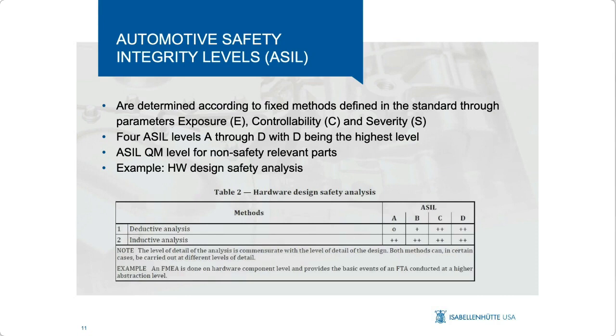Below you can see another example of a hardware design safety analysis. The proposed content here is a deductive analysis and an inductive analysis. And you can see that depending on the ASIL level that is supposed to be achieved, there are different levels of detail that have to be performed.